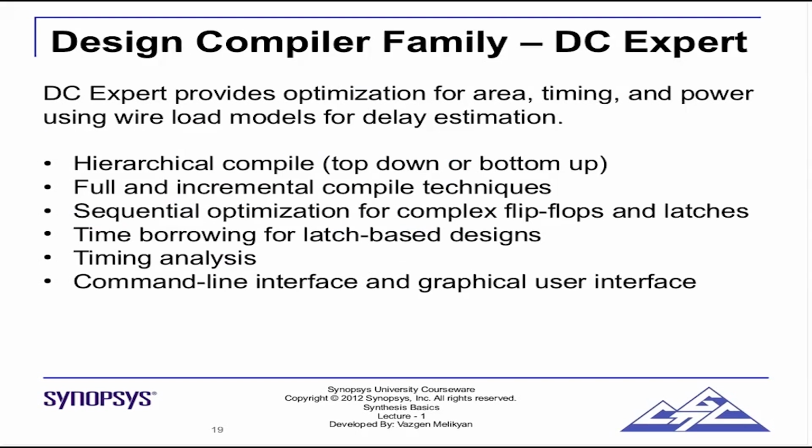The first and foremost tool we are looking at is DC Expert. So you don't have to actually start up different tools. When you start Design Compiler, we call it DC Shell. This is not a single tool, it has a bunch of tools inside it. So all commands will work there for all the tools. You don't have to worry about invoking different tools for different applications.